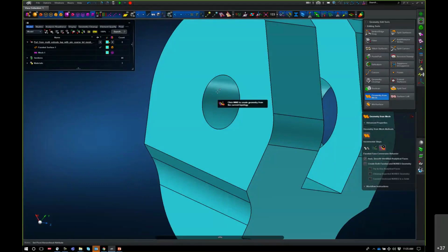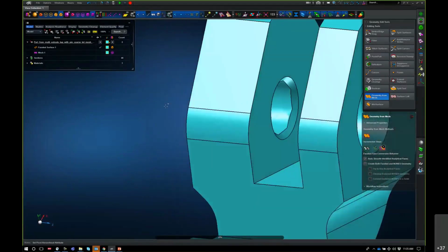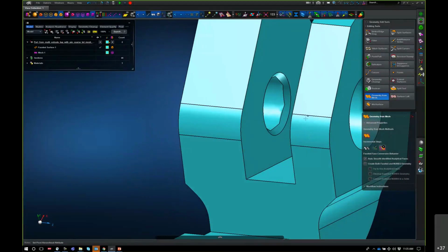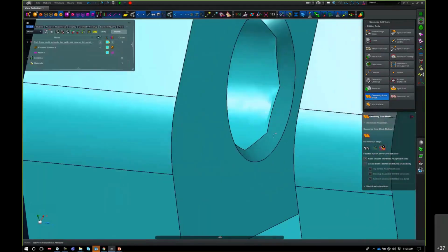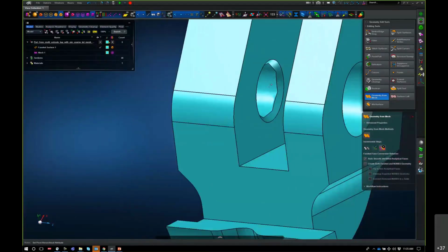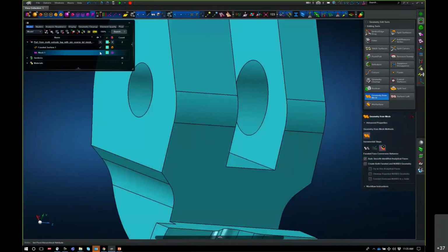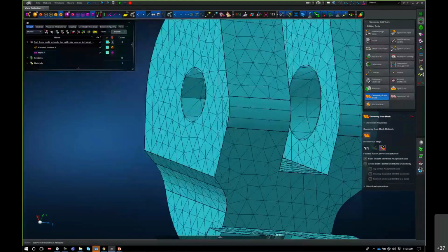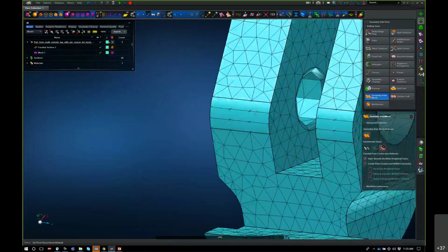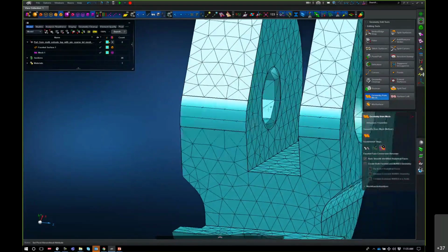Now, it's not perfect in this particular case. I have deliberately picked a model that has some issues. This cone was perfectly matched. Cylinder was matched, but we have a defect probably right here where it didn't understand between the two. So I do have facets here, so that's a problem. Now it has slightly finer mesh. This is deliberately made into a fairly coarse model. If it was slightly finer, this problem goes away. It is in the model, so I wanted to show you that kind of thing that happens.